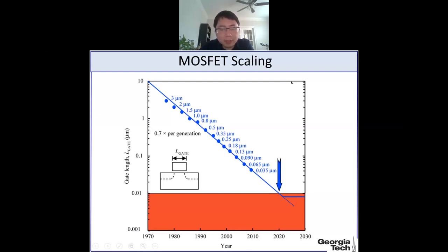The reason we use L as a metric is because it is the minimal feature size we can have for a particular technology node. So this is the smallest dimension in the transistor. And this is typically limited by the lithography of the technology node.